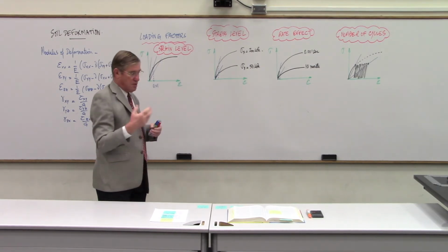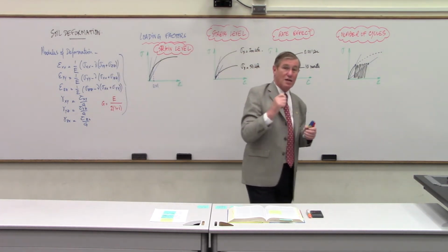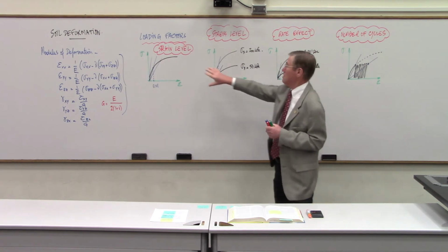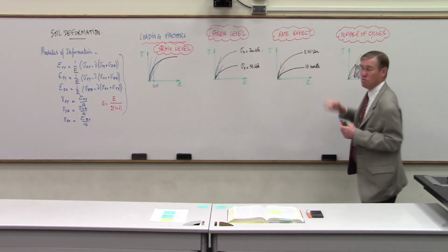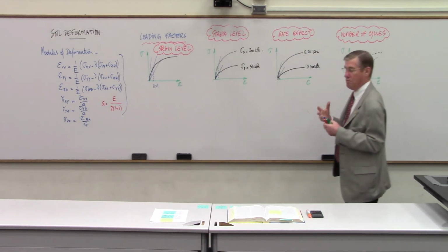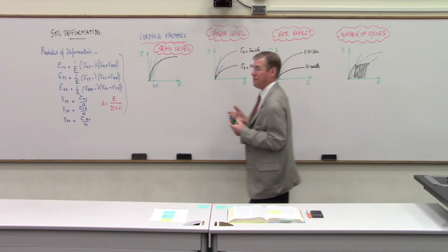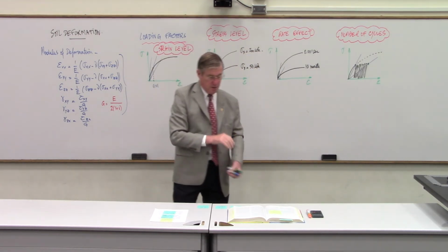So it's important, again, when you get a modulus, a soil modulus, that you ask the question, what is the strain level? What is the stress level? What is the rate effect that you're giving me? What is the number of cycles that you're giving me, so that you get a good feeling of what this modulus is going to represent.